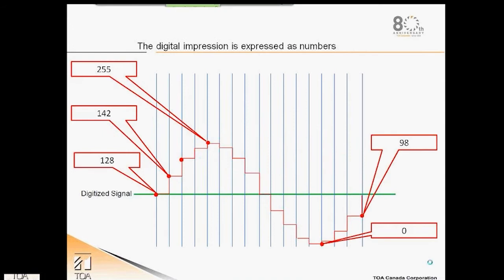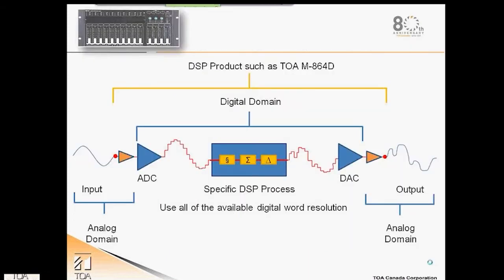Here we see the numeric equivalent expressed as a decimal number. Since this is an 8-bit word sample, the numbers will vary between 0 and 255 for a total of 256 data points. What the microprocessor sees and understands is really in a binary format, and in this case we have an 8-bit word. A representation of the decimal numbers in binary zeros and ones of 8 bits long is shown. Same information, just a different numbering system.